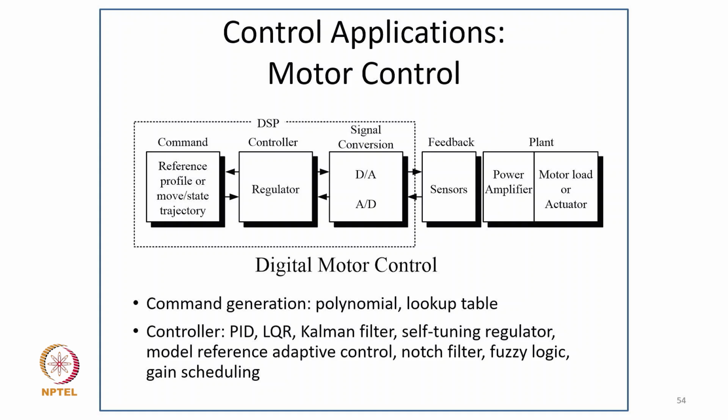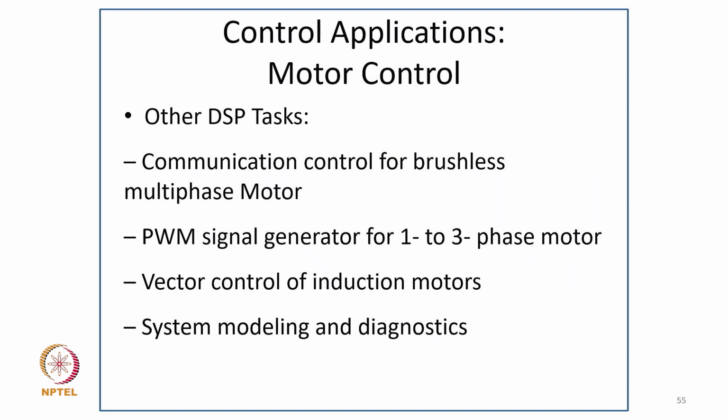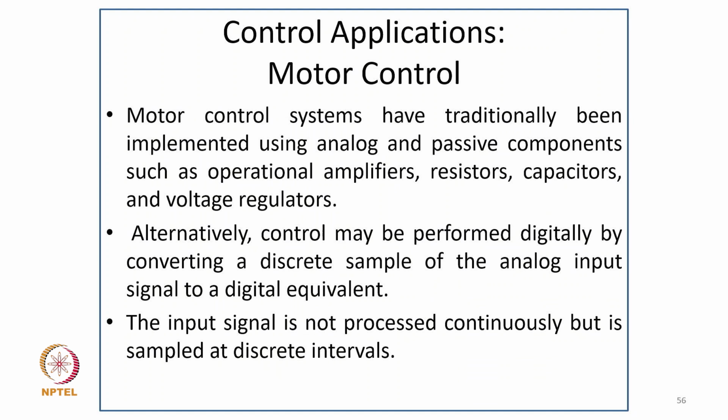So we have command generation as a polynomial lookup table, and control like PID, LQR, Kalman filter, self-tuning regulator, model reference adaptive control, notch filter, fuzzy logic, and gain scheduling. Then other DSP tasks are commutation control for brushless multi-phase motors, PWM signal generation for 1 to 3 phase motors, vector control of induction motors, and system modeling and diagnosis.